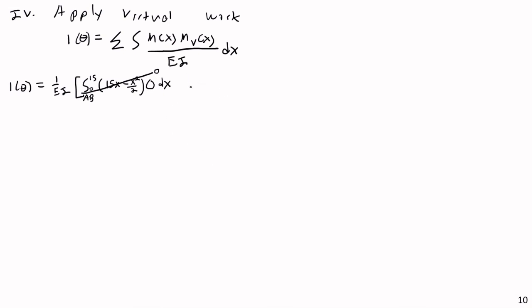So then, if I consider this here, I'm going to consider the beam plus the integral from 0 to 20, and this would be the integral on column BC, so I can put a little BC there if I like. Let's substitute in the appropriate expression, times, for the real moment expression, 112.5 plus 14.375x minus x squared, and then times 1/20th, 1 over 20, times x minus 1 dx. And we now have the full moment expression.